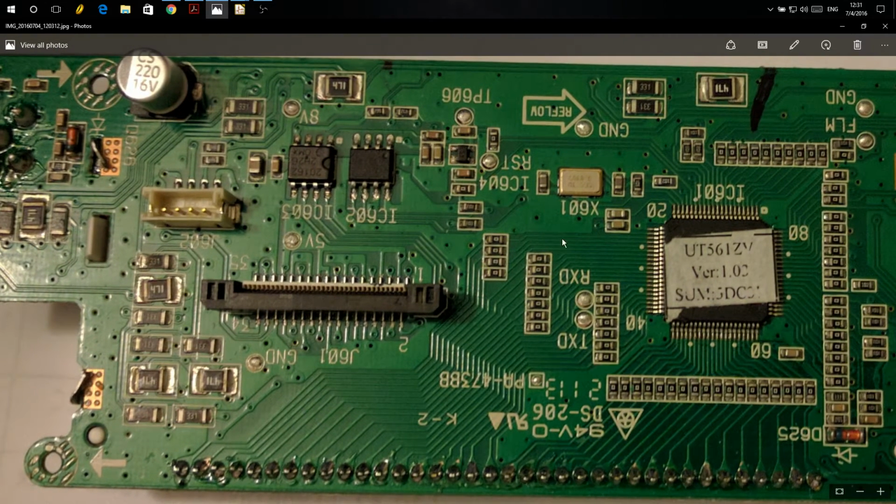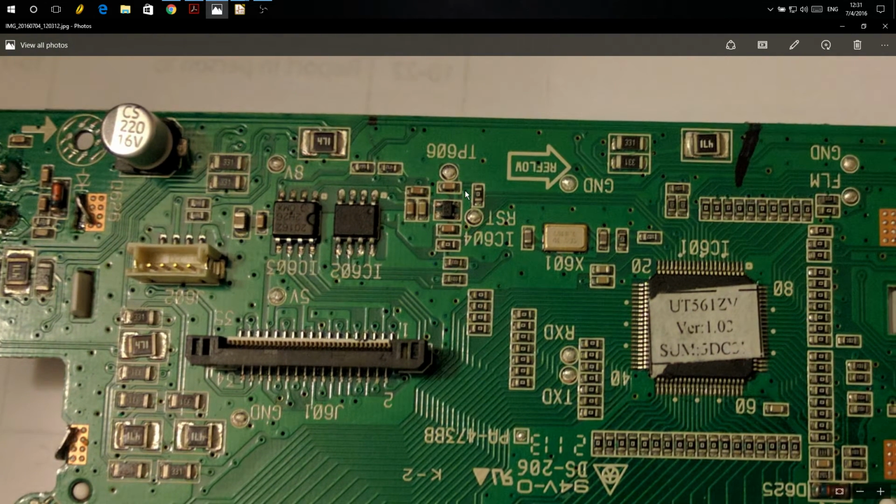But then the supervisor IC, a lot of times also called a reset IC. It's looking for the power conditions to be good, and then it issues a reset to the microcontroller. Basically, it just drags the reset pin low, and that's pretty much all it does. These are actually a common failure point in some electronics. They will short themselves to ground, and then you'll have something that appears dead, when in fact it's just because the reset line is being dragged down, it's being held in reset. So it doesn't do anything.